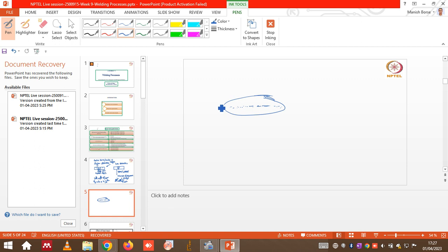Okay. And there are other difficulties in the case of laser beam welding and other high energy power density processes: there is no escape of the gases, right? And the metal can be subjected to porosity or segregation issues, which cannot be avoided, or that can be avoided with certain homogenization treatments.